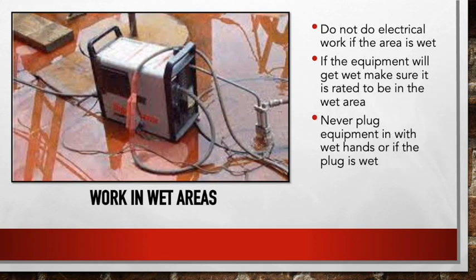All right, work in wet areas. Obviously, using electrical tools and equipment while standing in water is not a great idea. Some pretty easy ways: you can use elevated platforms, non-conductive work surfaces such as rubber mats, not pallets, obviously, because wood is conductive, especially when wet. Stone, etc., to prevent you from coming into contact with a potential circuit. And lifting the tools and cords out of the water is also an important component of this. So don't work around or with equipment if you're wet or anything's wet. You want to make sure everything's dry, as that is the intended atmosphere to work around electrical equipment.